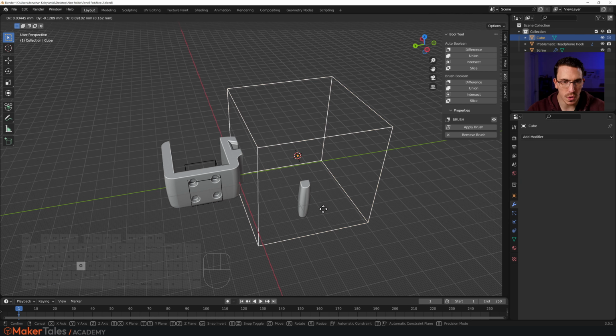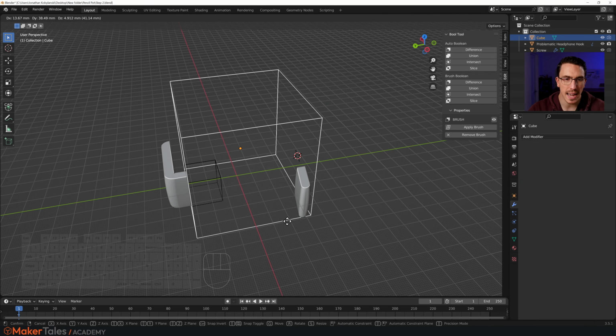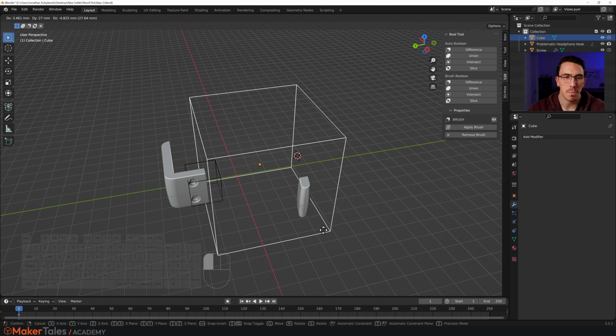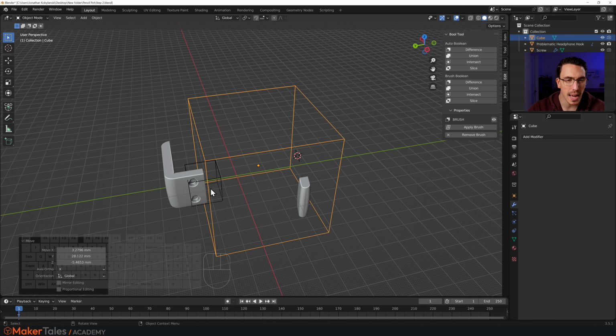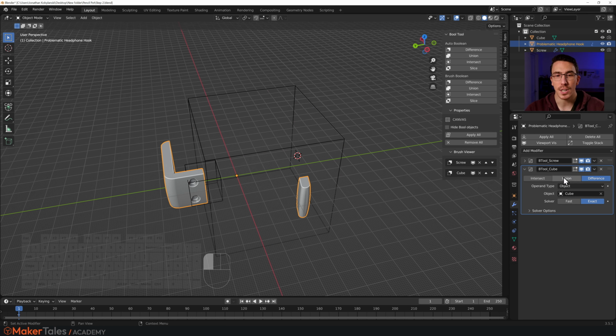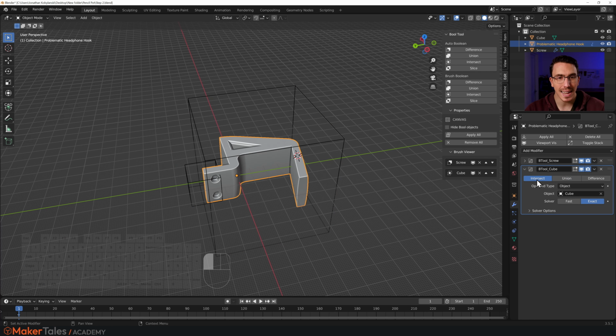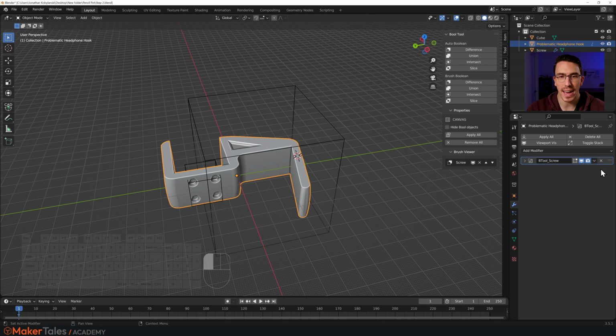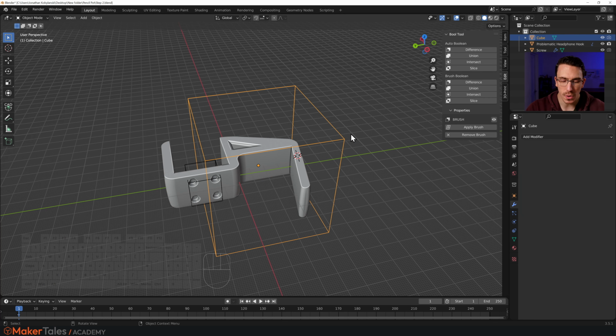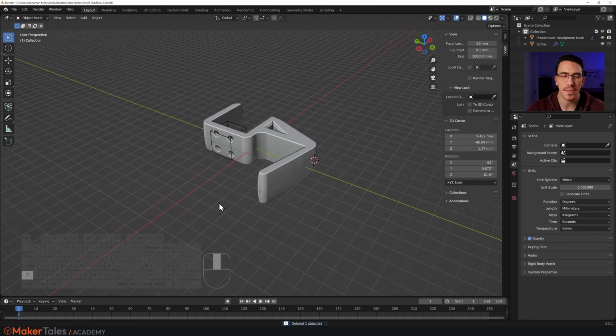You can do all this lovely motion here. You can have multi-booleans. Boolean to another Boolean is okay. It's when the Booleans are their same mesh, it doesn't work correctly. We can change this by going into the properties and change this to a union, so that is adding it, intersect, that is the bit inside. And you can remove a lovely modifier by clicking this little X, which removes it. We can go here, remove that mesh, we don't need that there.